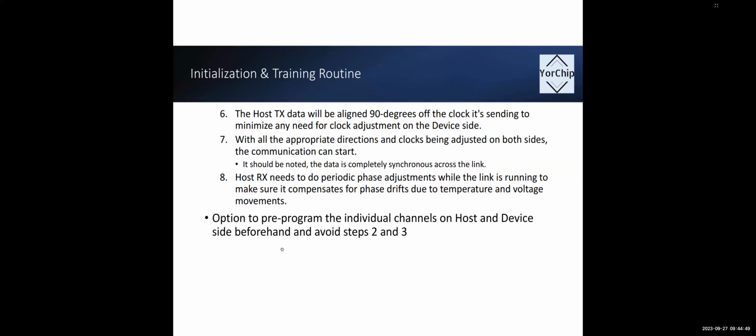Yeah, and one implicit addition that this 90-degree offset brings, again at lower speed with all those hypotheticals, is that it keeps the clock thinner while the data is being transmitted. Because we're using the same clock for transmitting on the other side, it reduces a bit the data-dependent jitter on the clock.